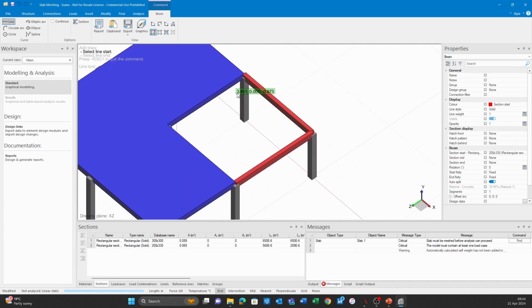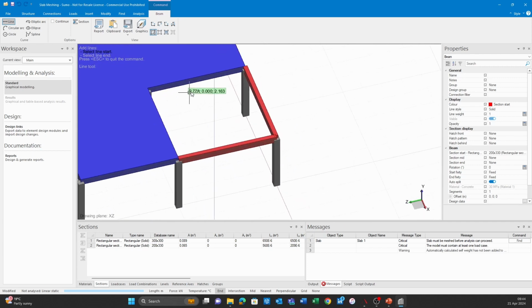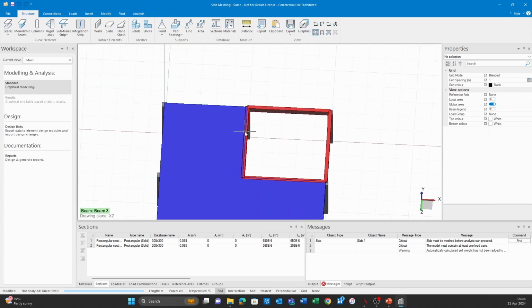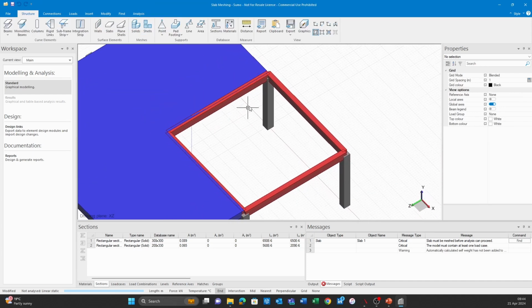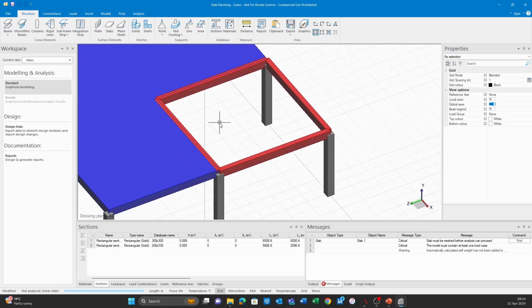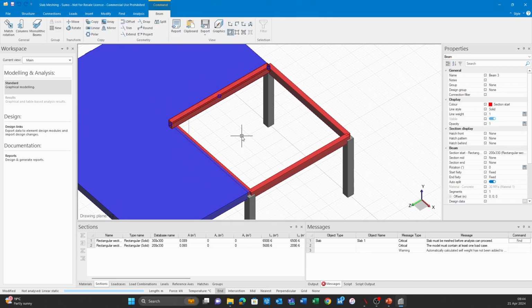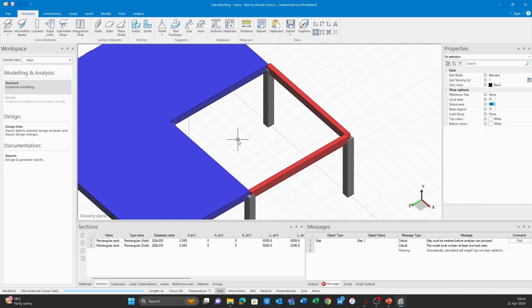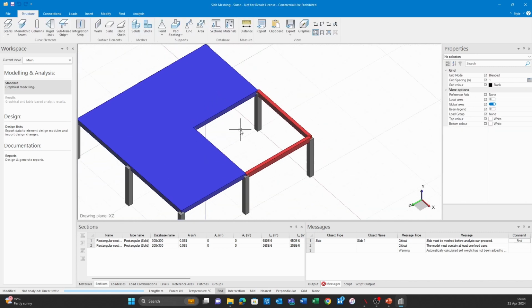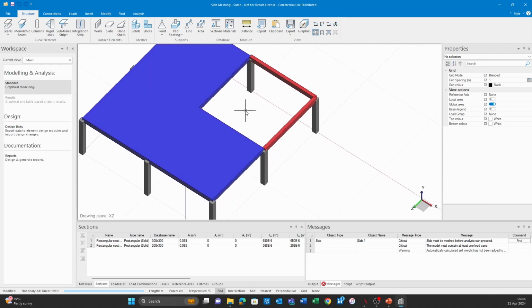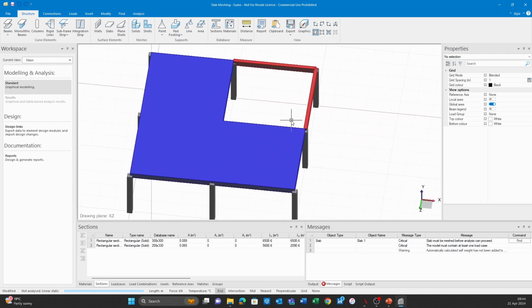So what you could also do then is, if you're concerned about what you've cut out, so just the 200 by 330 on that side, you can also add a beam there. Now, the only thing is here that it will make this section here much stiffer than what it actually is. So in that regard, you can add an additional point, area load to this, or whatever you feel like would be good.